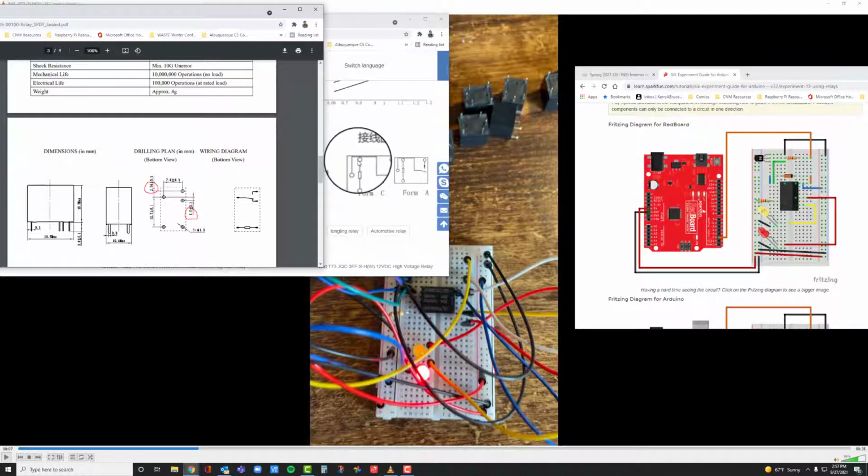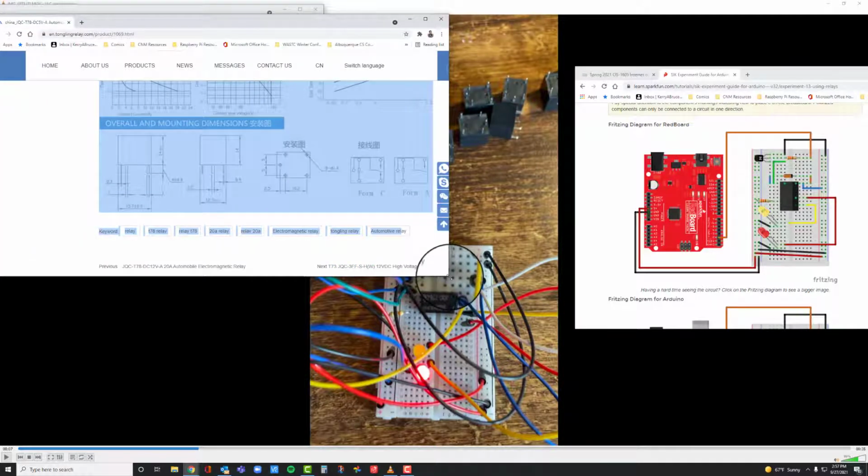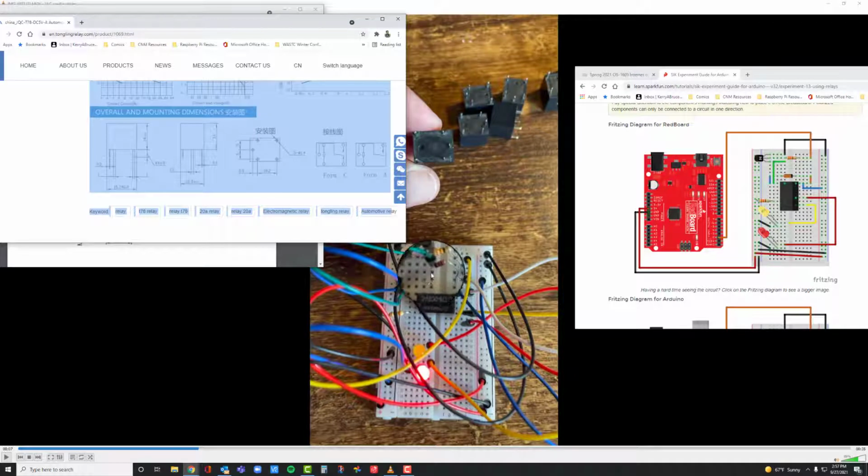The other possible thing, like if you wire it and you move these 2 wires over to this side, and you move this resistor up to the middle, and the yellow up to the top, and the red to the bottom, right, and you're still not getting movement, what you may want to then consider is this diode here. Remember, because the diode is only one direction, which, by the way, this is actually plugged in backwards. The black should be on this side over here. You may want to switch this around, because the current may be only going one direction. So I would try that.